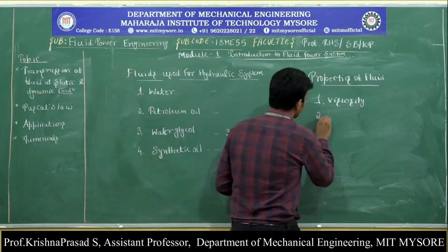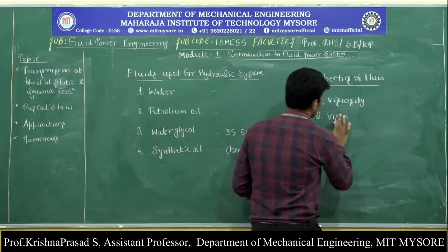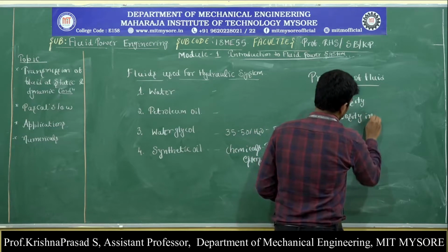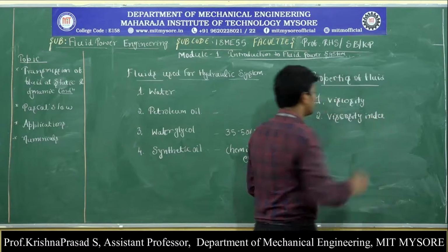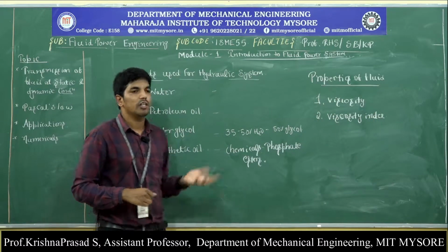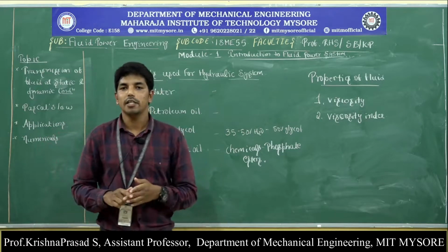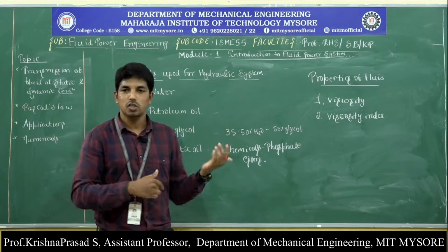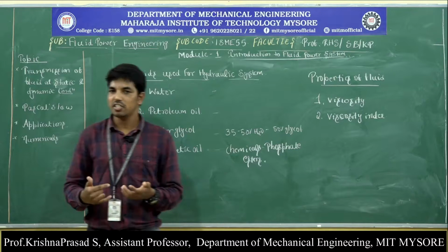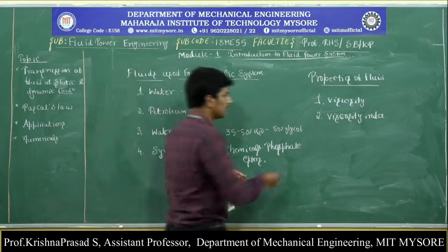Next, the second one is viscosity index. The fluid should provide the correct viscosity during the complete operation. That means as the fluid flows from one place to another through the hydraulic components, it does not lose its viscosity at any stage. That's why the viscosity index should be at a proper condition.